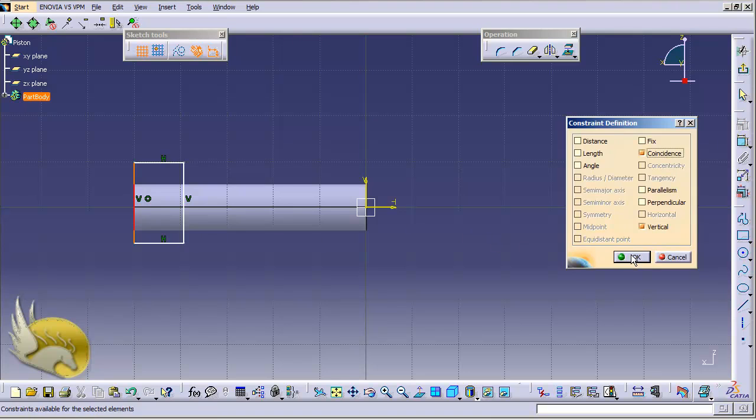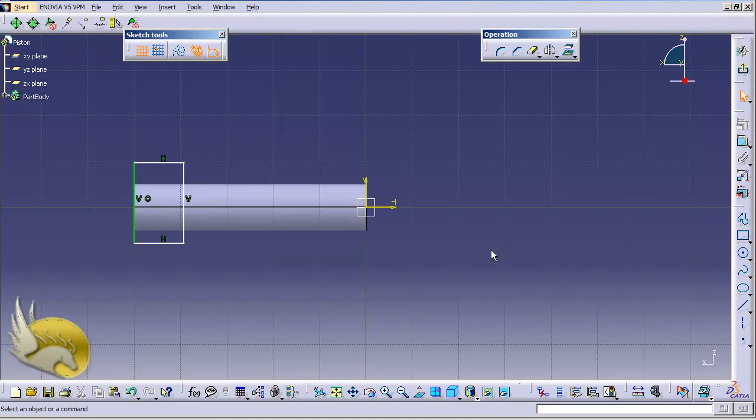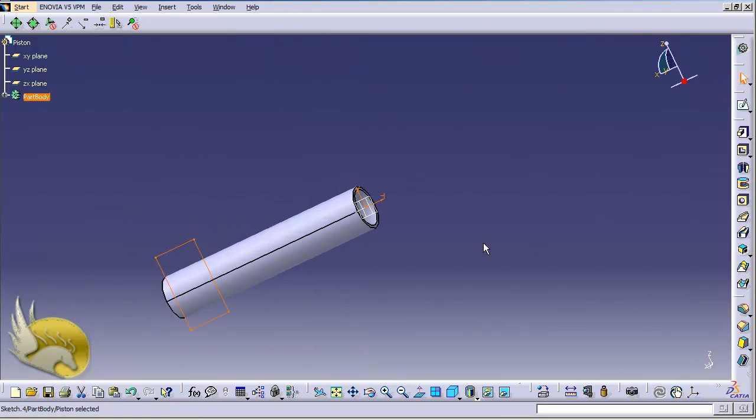and this will go to the left, to the right. It should be about 10 millimeters in this direction, and it should be exactly 10, but this side is not that important. I can add any constraint here, but just want to make sure that this is 10 millimeters. So I exit my workbench, and I want to have a pocket here.